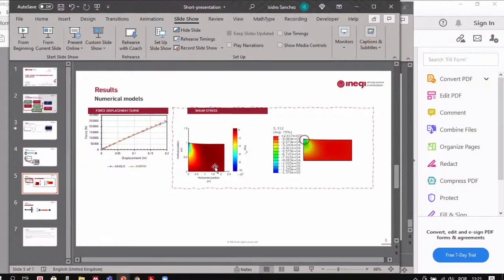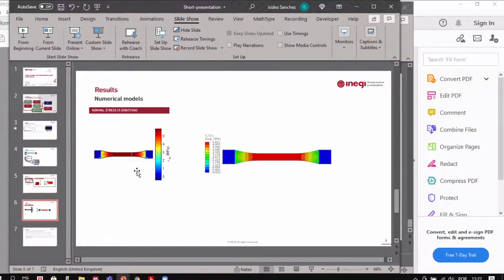And we compared normal and shear stresses. I am presenting here the shear because it allowed me to see if there is a difference in the magnitude and in the pattern, and also if there is a problem with the polar decomposition during the implementation. And we can see that everything looks right, the magnitudes are right, even in the little excess concentration in the tip. The same applied for the dog bone shape specimen.